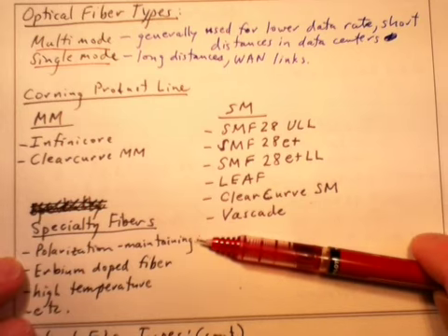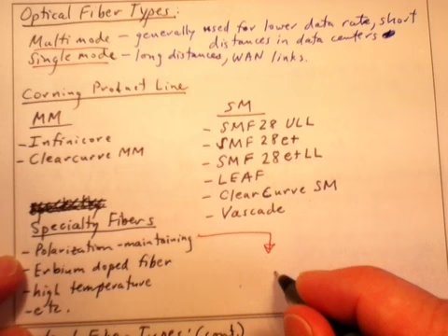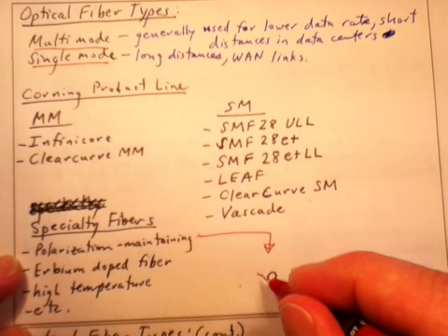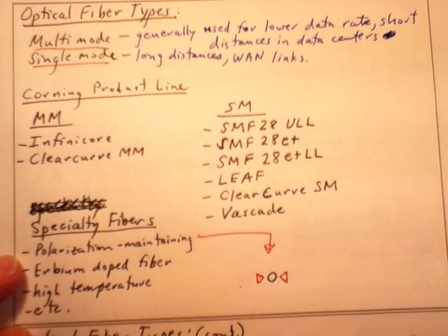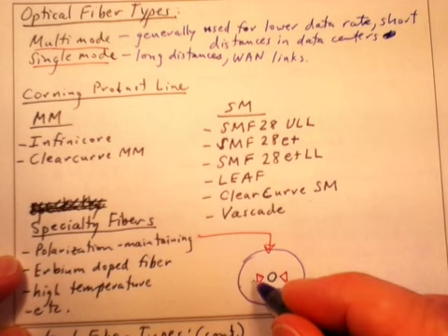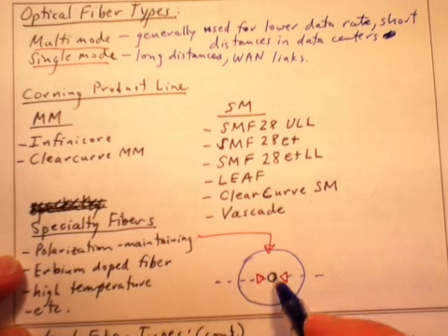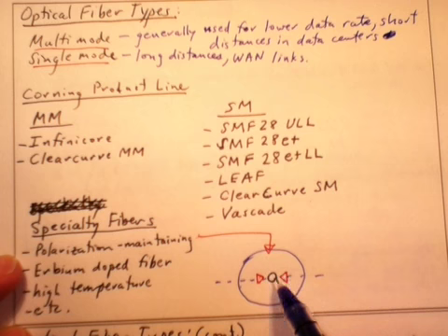And in polarization maintaining fiber there is a particular axis of symmetry in the fiber, and in fact what they do is they have the core, but then as part of the manufacture they put some sort of a stress into the glass surrounding the core. Out in the cladding here they'll put some sort of a stress on that glass which will cause the core to be birefringent, and in a birefringent material you have very different refractive indices for the directions of polarization.